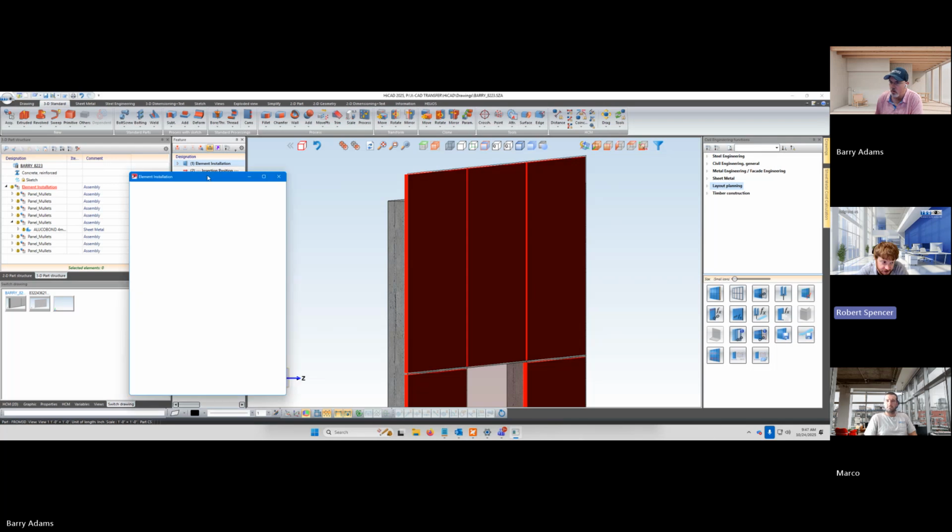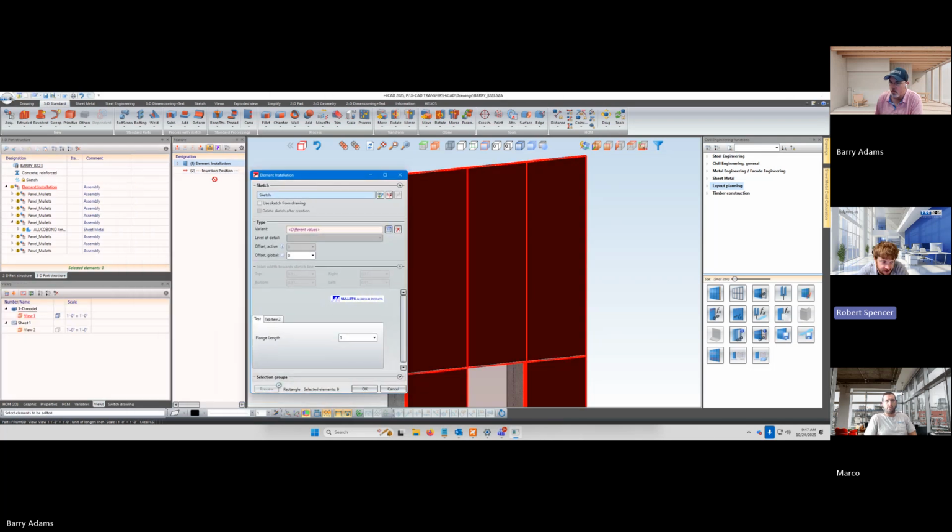So you understand the difference, right? You got your part tree, which shows the assemblies and the panels and the parts, and then the feature tree. The feature tree shows all your sheet metal, flange, whatever else, miter. When you're working here on the elevation, your feature tree shows step 1 element installation, because that's how the parts were created here in the elevation workspace, we'll call it. And as you can see, it comes right up.